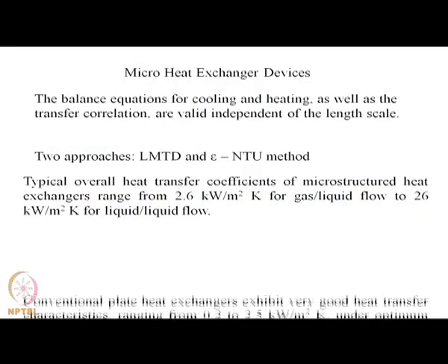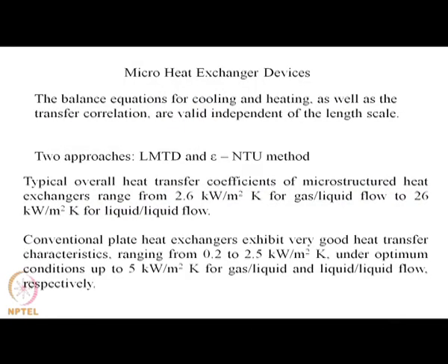So, just to give you an idea of what the typical overall heat transfer coefficients of microstructured heat exchangers are, they range from 2.6 kilowatt per meter square for gas liquid to 26 kilowatt per meter square for liquid flow.